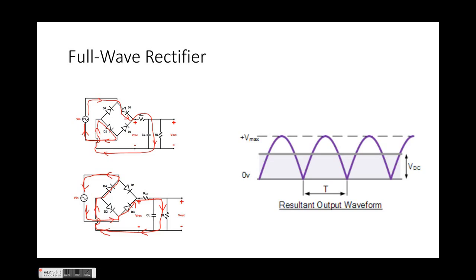I chose this figure specifically because our pre-work specified that we're using ideal diodes, which do not have a threshold voltage. As soon as voltage equals 0, our diode is going to short. So we don't have a threshold voltage. But if we were using a constant voltage model for our diodes, at the bottom of these peaks we would have a little gap, and that would be our threshold voltage gap, in the time where the source is actually going to be an open rather than just letting voltage flow through.